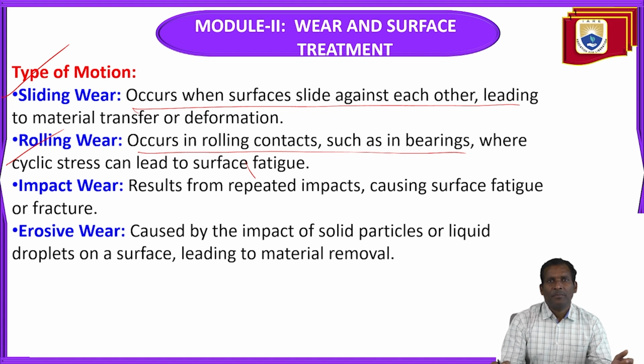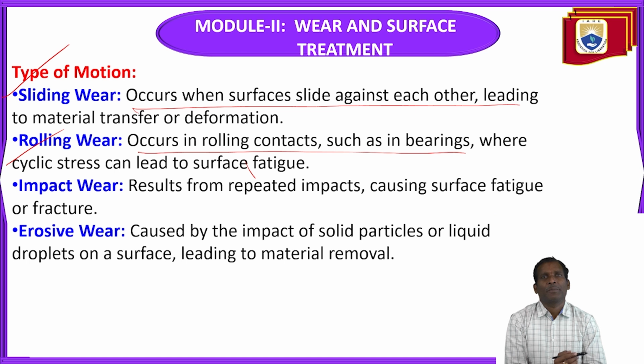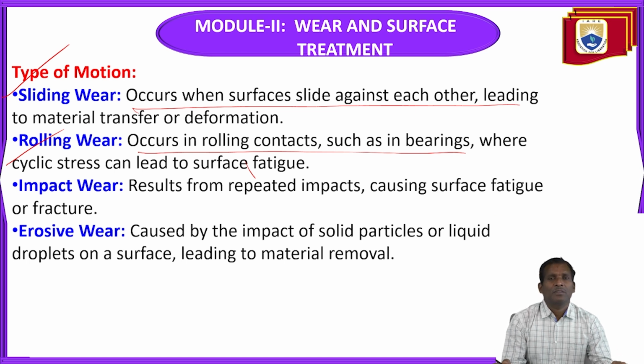Similarly, impact wear results from repeated impacts causing surface fatigue or fracture. Already I have studied this in fatigue phenomena. It results from repeated loads, the component subjected to repeated loads, repeated impacts causing surface failure. So that is impact wear. Rolling wear occurs in rolling contacts like rolling contact bearings, where cyclic stress can lead to surface fatigue,